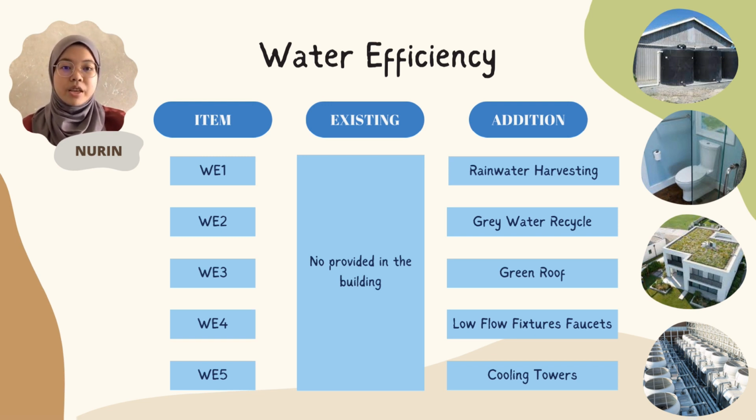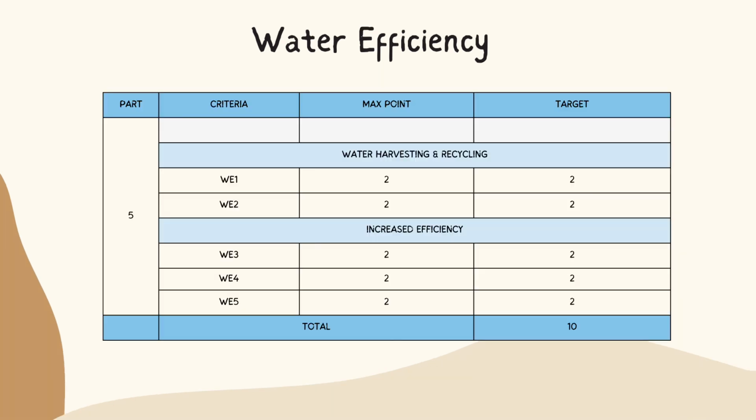Last but not least for me, for the innovative building, we aim to use sub-meters to monitor and manage major water usage for cooling towers, irrigation, kitchen, and tenancy use. Evaporative cooling systems are used in the building to conserve energy. Besides, we also aim to link all the water sub-meters to the EMS to facilitate early detection of water leakage at the new building to earn 1 point for the assessment.